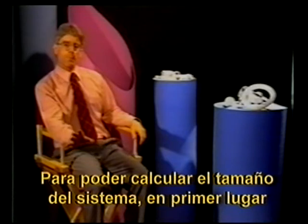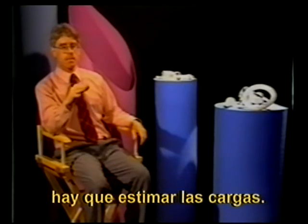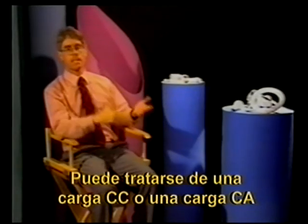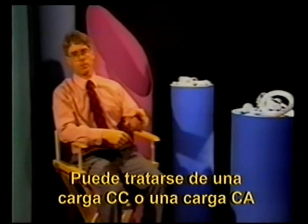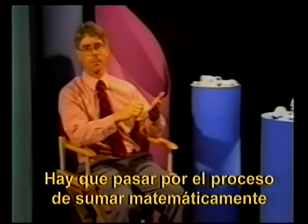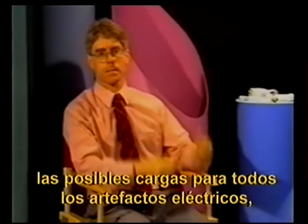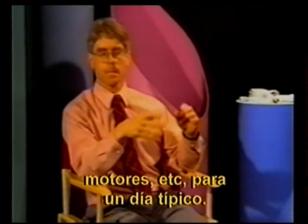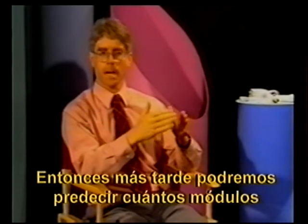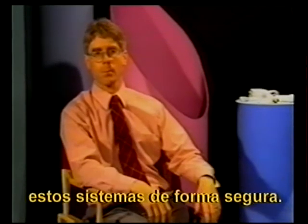What we need to do in order to do our system sizing calculations is first estimate our loads. We might have DC loads, you might have AC loads. We need to go through a process of mathematically adding up what the various lighting, motor, appliance, device loads might be in a typical day. Then later, we'll be able to predict how many modules and how many batteries we need to safely operate those systems.